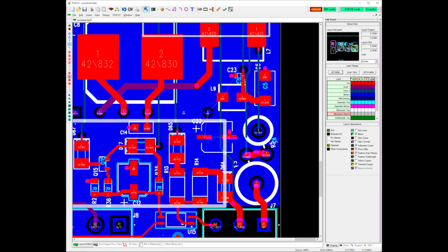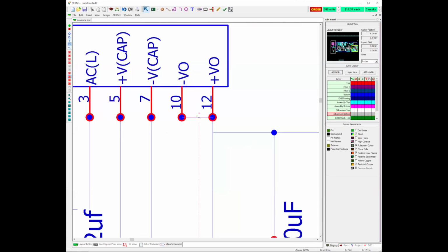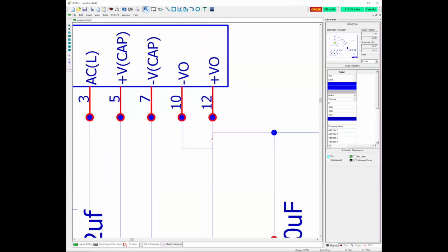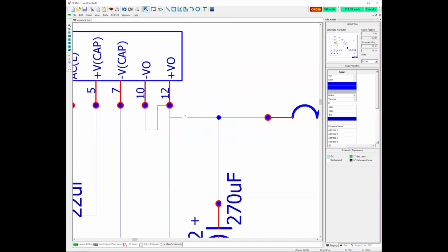Well, now that you've got that wire in there, it's really hard to grab it and pull it out and disconnect it from an unintentional connection. These are 2 pins apart, so there's enough room. But if this part was made smaller and these pins were close together, I wouldn't. If there wasn't a separate grid point in between here, I couldn't select that wire and pull it out and do away with it. But also, if I do away with it, I'm also going to do away with all the routing that went to other things from that pin.